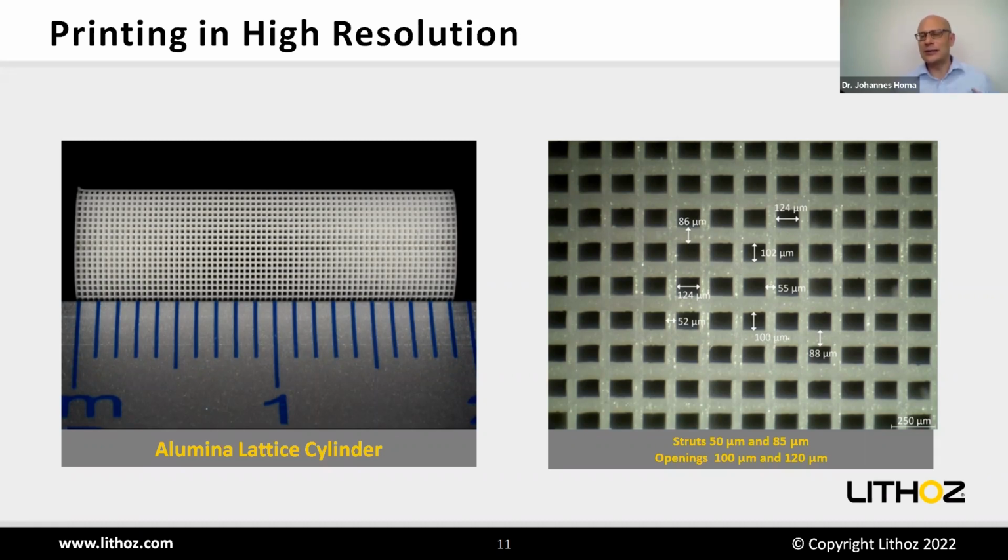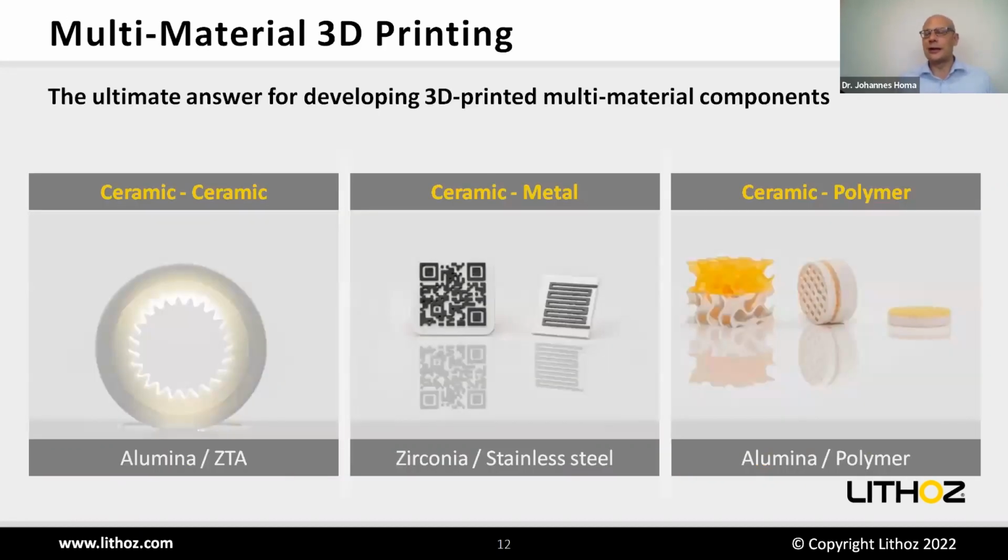This is really the very end, and these lithography-based technologies are more used for smaller parts with thinner wall thicknesses. There is definitely a limitation in the wall thickness, because we are using a photopolymer binder with a very high ratio, and therefore the binder burnout is difficult, and we cannot make walls thicker than maybe a maximum of 10 millimeters or so. So if you want to make bigger parts, you need to make thicker parts, and this is why we are going for the LCM technology.